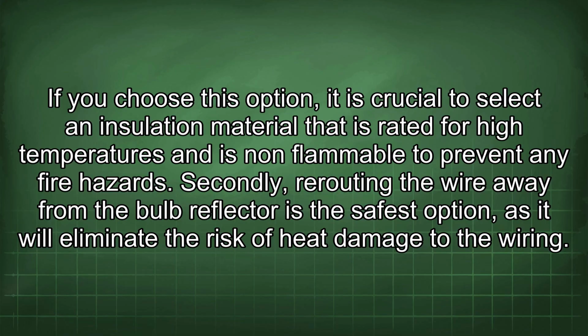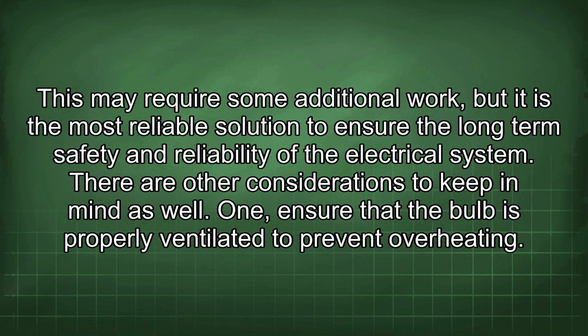Secondly, rerouting the wire away from the bulb reflector is the safest option, as it will eliminate the risk of heat damage to the wiring. This may require some additional work, but it is the most reliable solution to ensure the long-term safety and reliability of the electrical system. There are other considerations to keep in mind as well.